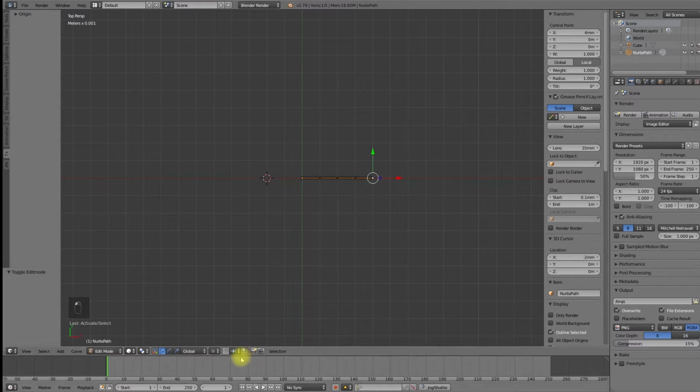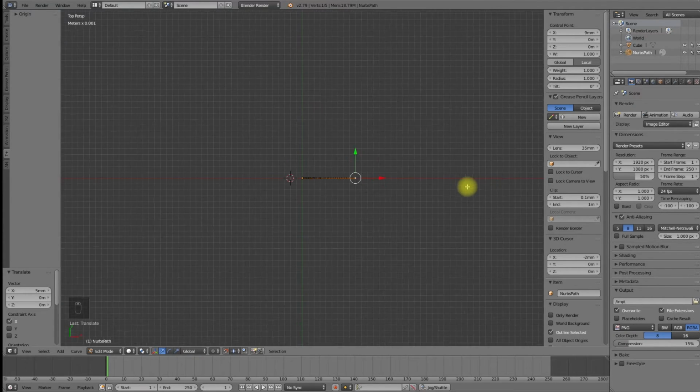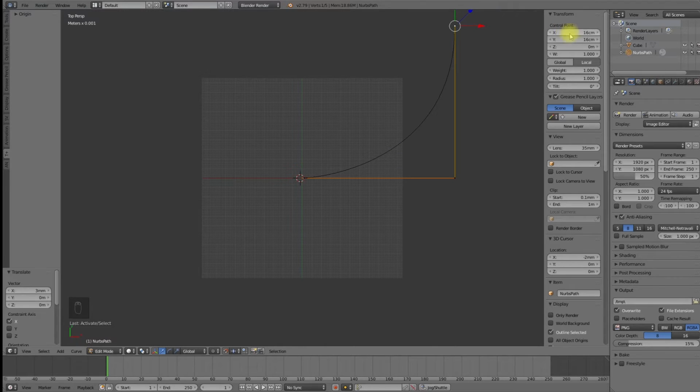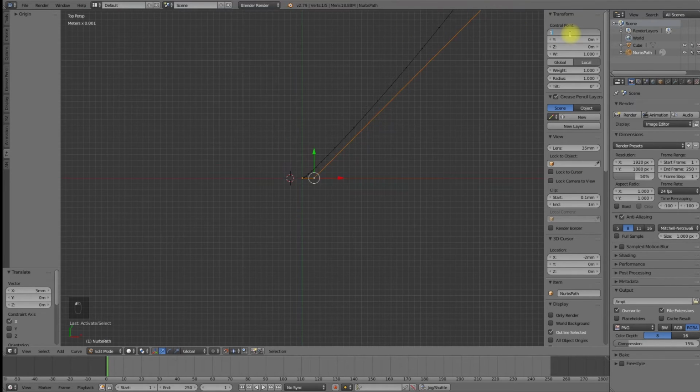The control points of the curve can be shifted very precisely in the top level view and the orthogonal perspective. For faster modeling, use the numeric input: G key, axis and movement distance.